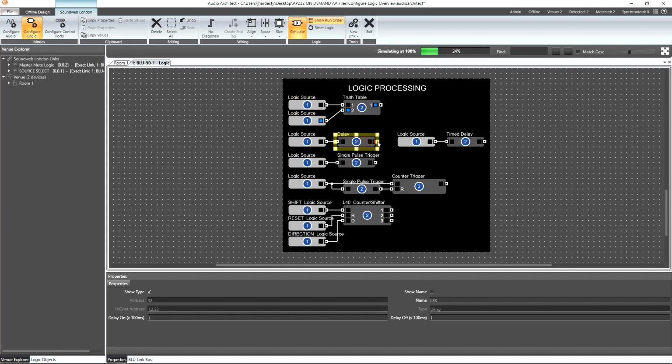Next, we have 2 objects that can deal with time. They are the delay and time delay. They both essentially function the same way, but the way we enter time into each differs. Take, for instance, the time delay. It allows us to work with longer amounts of time by entering the value in as seconds. The delay allows us to enter time as multiplied by 100 milliseconds, or a tenth of a second. Let's look at the time delay since it'll be easier to see how it works.